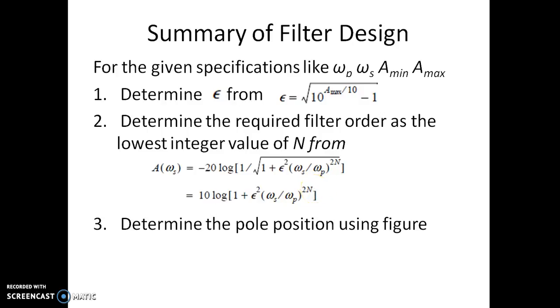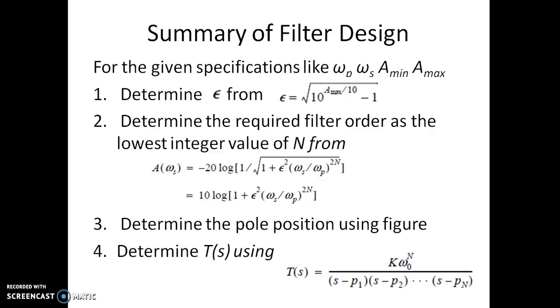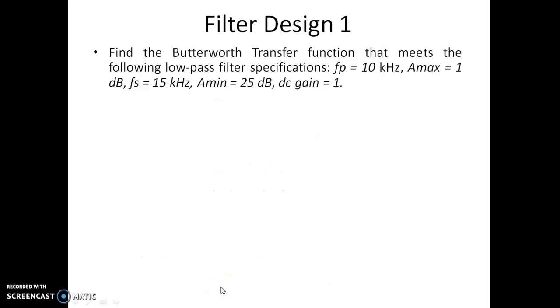Next, we should determine the pole positions using the figure, the figure we discussed in the previous slides. Then determine the transfer function. Since we know the pole positions, and since they are on the left hand side of the S-plane, we can write their positions and we can write the overall transfer function.